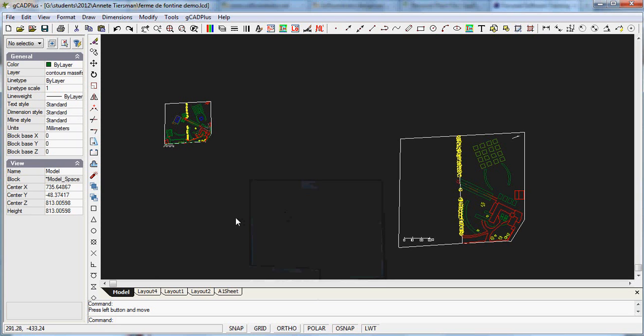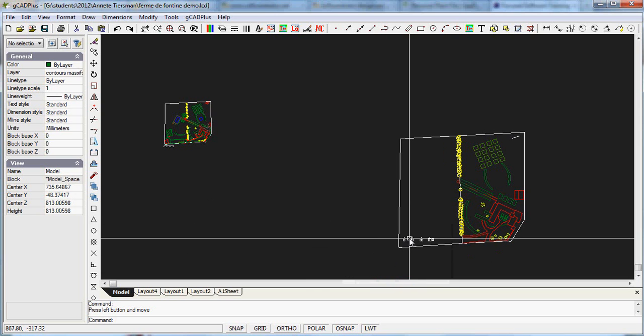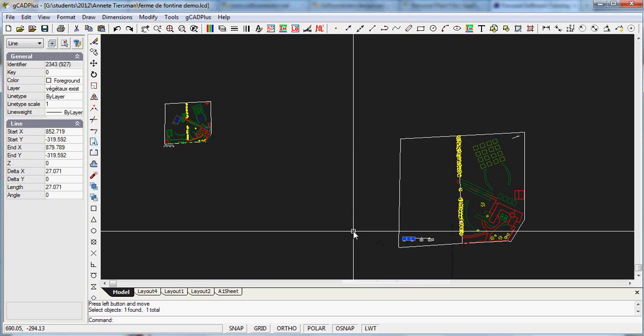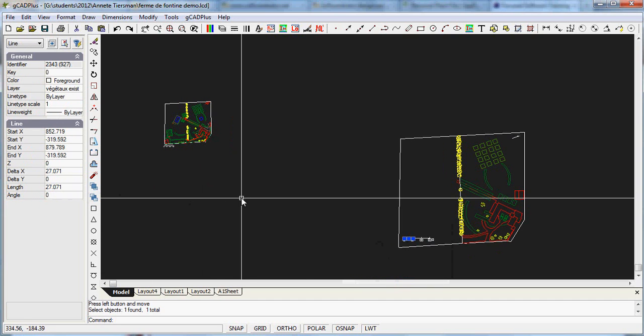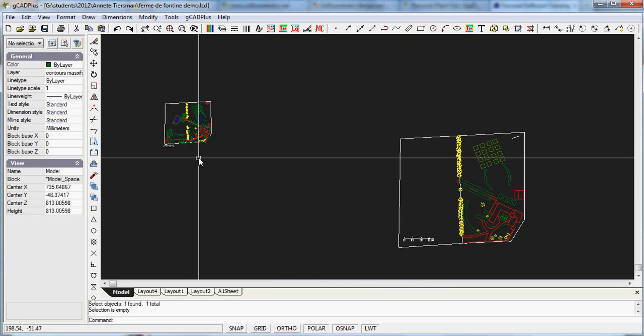Perhaps because of the way in which this drawing has been constructed and the way that layout tabs have been set, I'm having a great deal of difficulty managing the drawing. For example, if I click the layout over here, that we were looking at has been duplicated here and clearly been scaled. So if I select that little 10-unit marker there, you can see here its length is 27.071, whereas back in the smaller version it was an accurate 10-unit length.